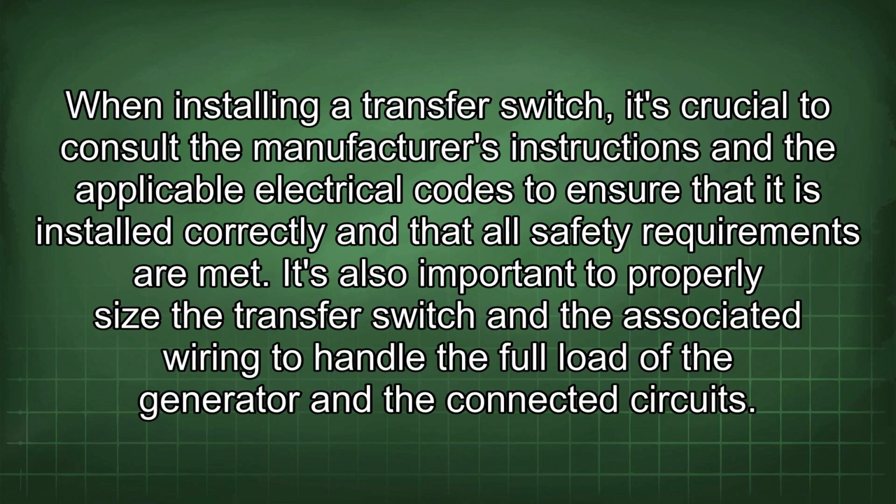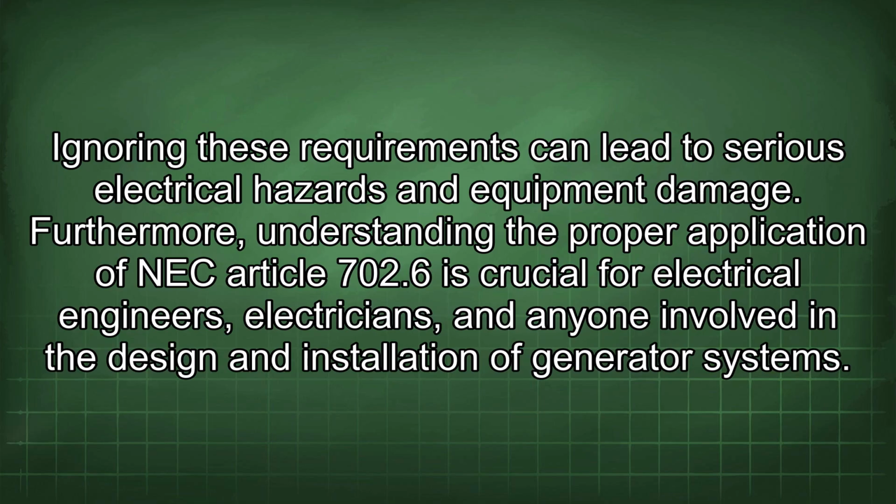When installing a transfer switch, it's crucial to consult the manufacturer's instructions and the applicable electrical codes to ensure that it is installed correctly and that all safety requirements are met. It's also important to properly size the transfer switch and the associated wiring to handle the full load of the generator and the connected circuits. Ignoring these requirements can lead to serious electrical hazards and equipment damage.